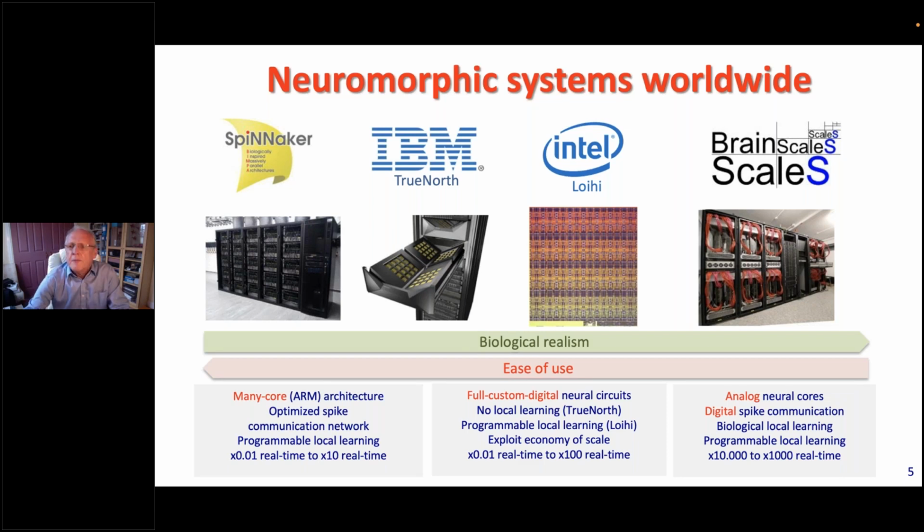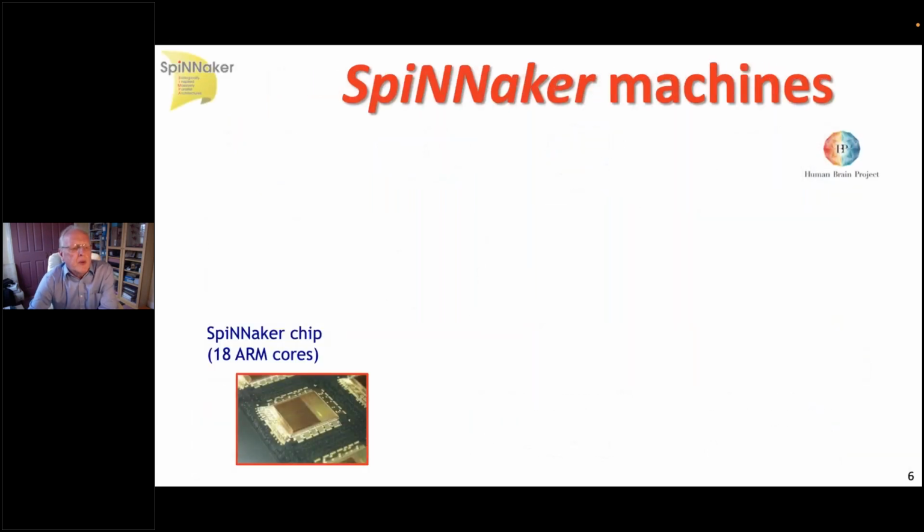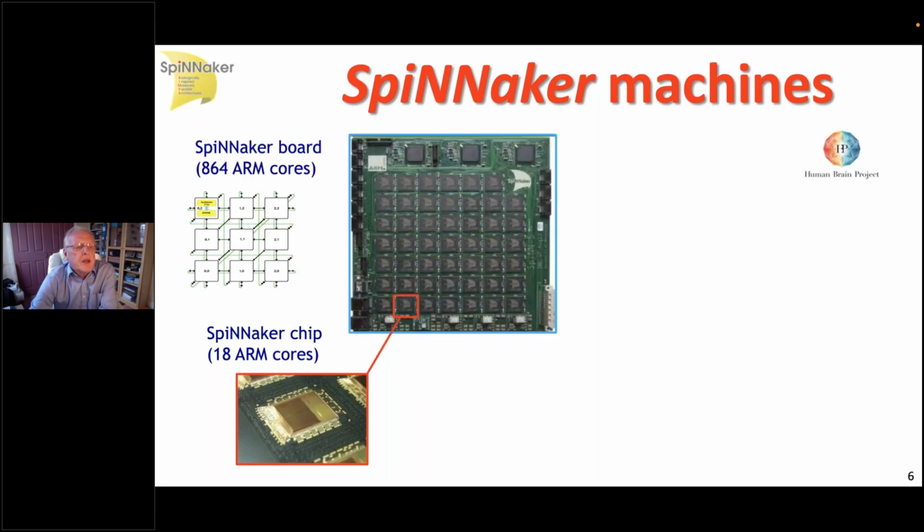So if we look at the example that I'm responsible for, which is the SpiNNaker machine, we started by designing a chip, and in the package there are in fact two chips. The lower lighter colored square chip is the compute layer, and the darker rectangle on top is industry standard memory, and those can be packaged, and then those packages can be arranged on a 2D surface of almost unlimited scale.